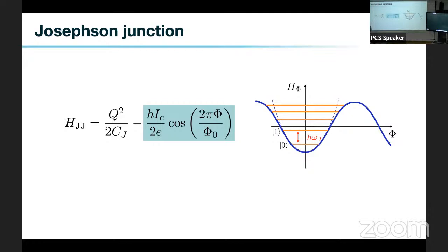At the beginning of superconducting circuits, there was a very short coherence time because of the charge noise. And if you assume there is a big anharmonicity, then it becomes very sensitive to the charge noise, so it reduces the coherence time. That's why people generally consider a small anharmonicity. If we adopt this parameter regime, it can suppress the charge noise. I see. Using this way, people achieve 100 microseconds or above. So this anharmonicity is enough to suppress the transitions from 1 to 2 that you don't want? Yes. Anharmonicity should be a finite number.